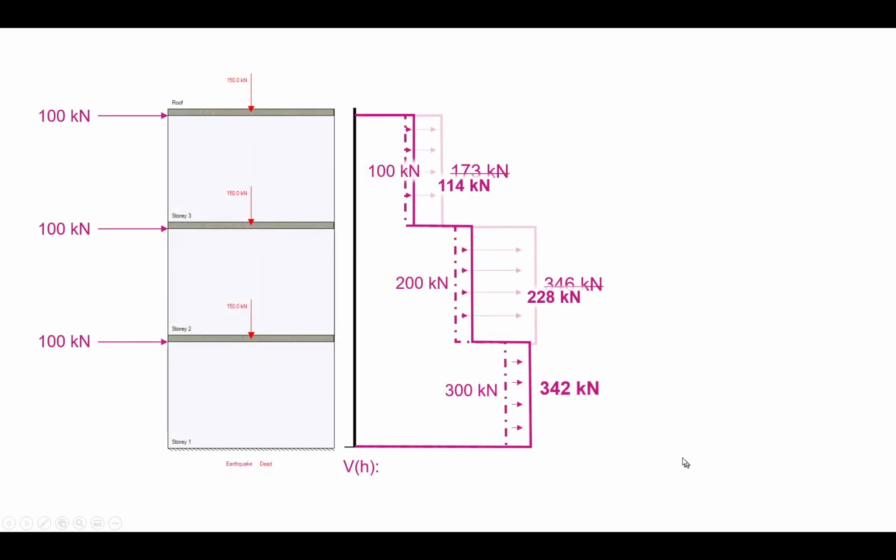So then going back to that shear envelope, using that 14%, rather than doing it differently and independently for each floor, we figured out what we needed at the base. So this is what our answers change to if we use that 14% for the entire height of the shear wall. And hopefully, after going through this, you might think it's more reasonable that we figured out the very base, and we are satisfying this clause for the entire wall. That is what we're looking at changing the software to for the next minor release.